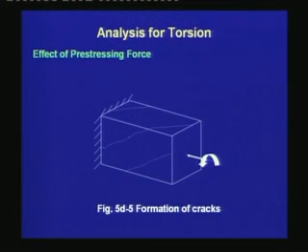The formation of cracks is as follows: with the increase in the torque, we will observe cracks in the beam which are inclined at an angle less than 45 degrees to the axis of the member. The crack width will be smaller, and the expansion of the beam that occurs for a reinforced concrete beam will not be observed here much.